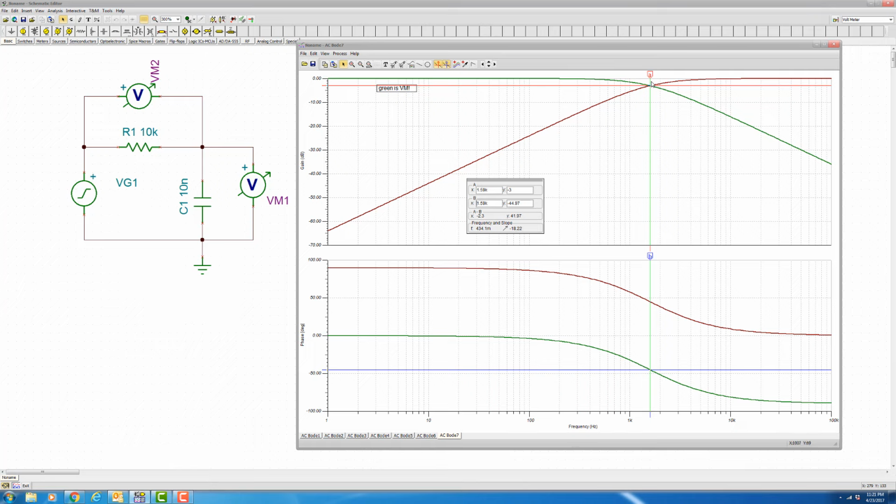So at the cutoff frequency of 3 dB down, it's a 45 degrees phase shift relative to what? 45 degrees from what? From our function generator. It's negative. What does that mean? That would mean if you looked at it on a scope that this is behind. So if this voltage was at its peak of 1 volt, this voltage would be behind a little bit. So that's called lagging. If you look at the resistor, it's at plus 45 degrees down here. So it's leading. The voltage here is leading.